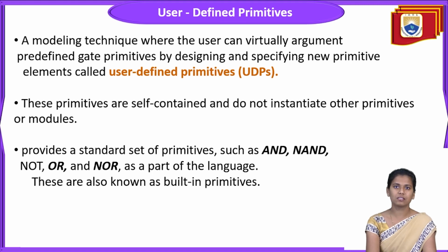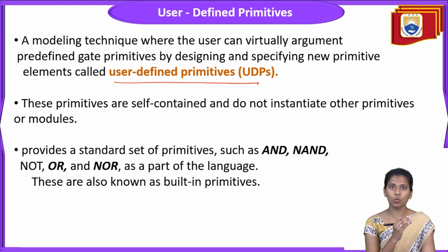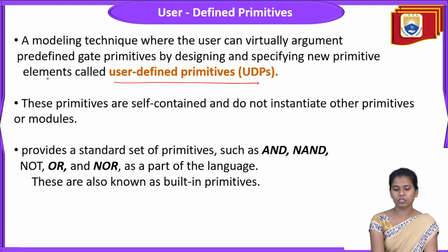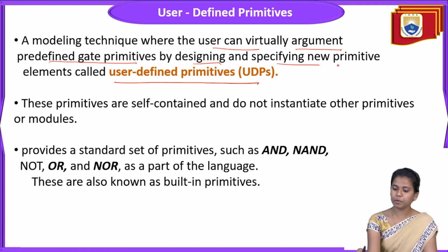Coming to user-defined primitives, let us discuss what a user-defined primitive is. Just ponder on the definition. The statement talks about a modeling technique where the user can virtually augment predefined gate primitives by designing and specifying new primitive elements.